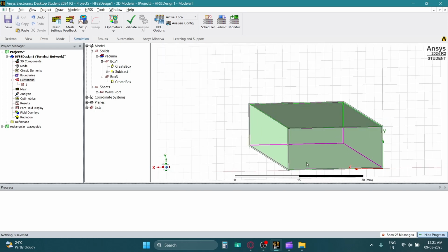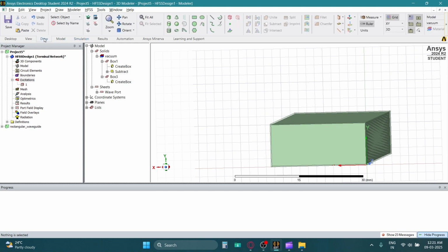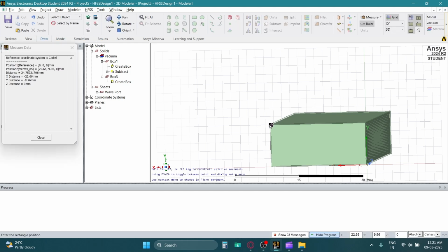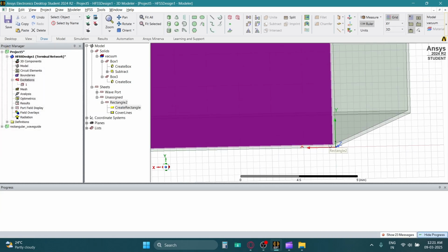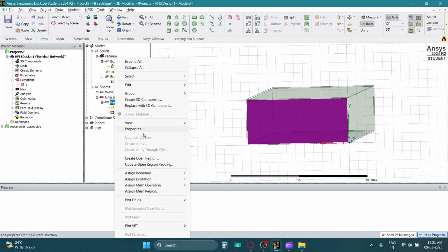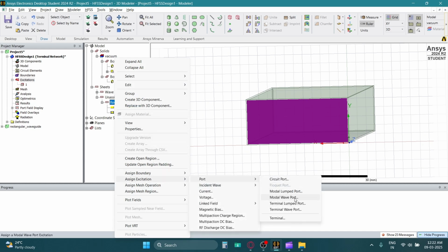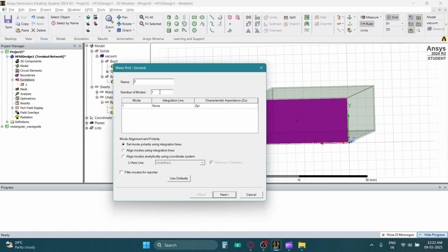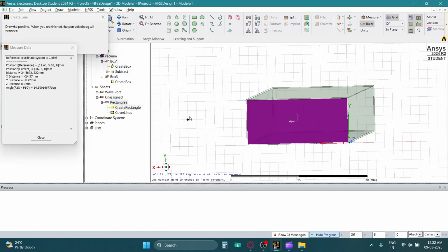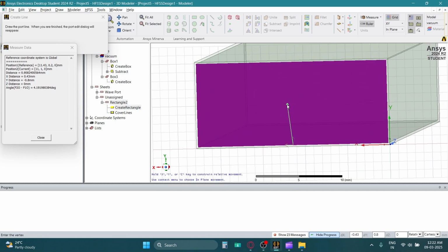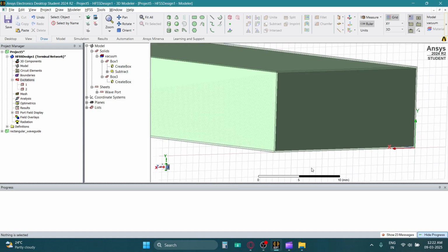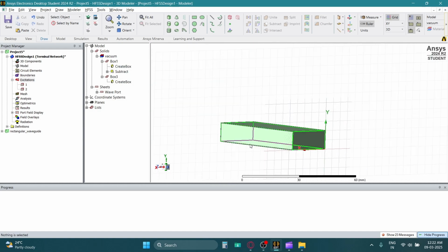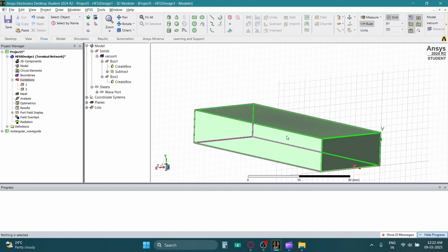So go ahead and add the rectangle, same as usual. Then you will assign this excitation port, model wave port, change these to 4 modes. You will get in the new line just triangle to triangle. Now we are done with assigning the wave ports, and now we will have to assign the radiation box.